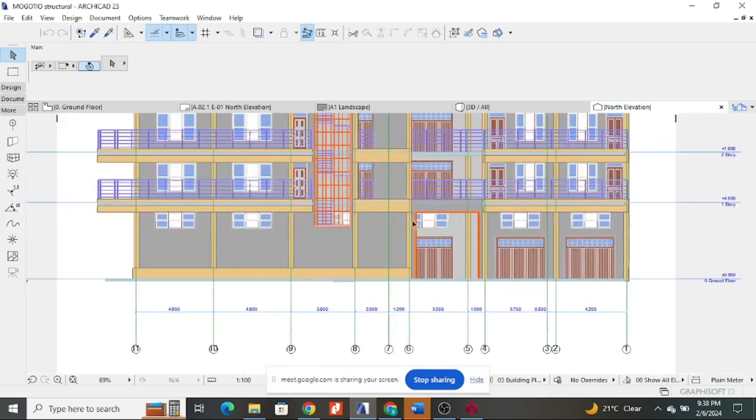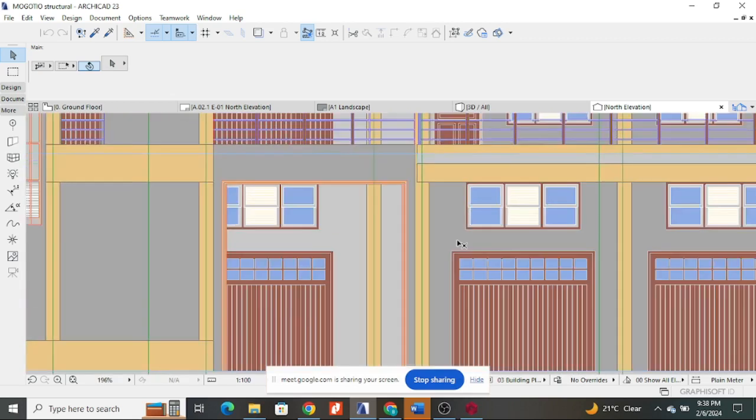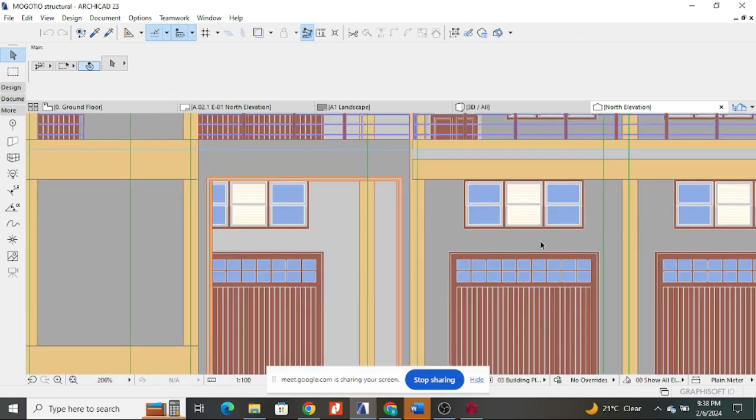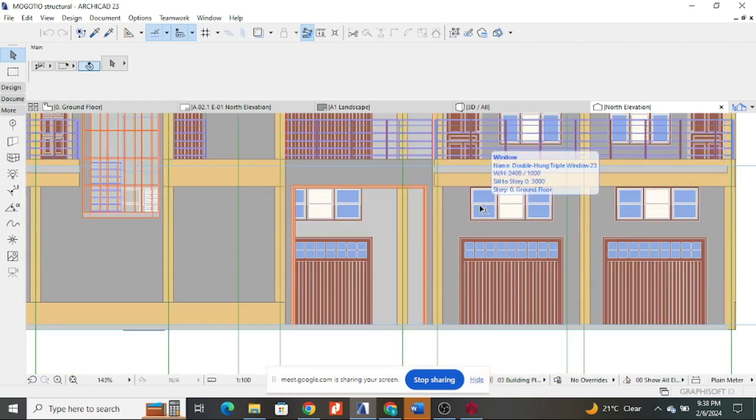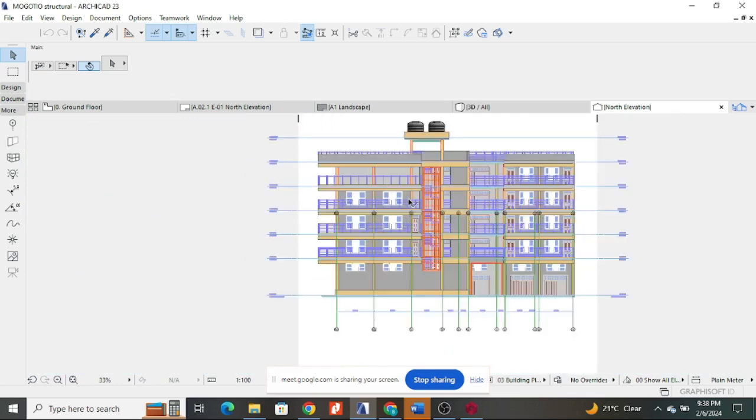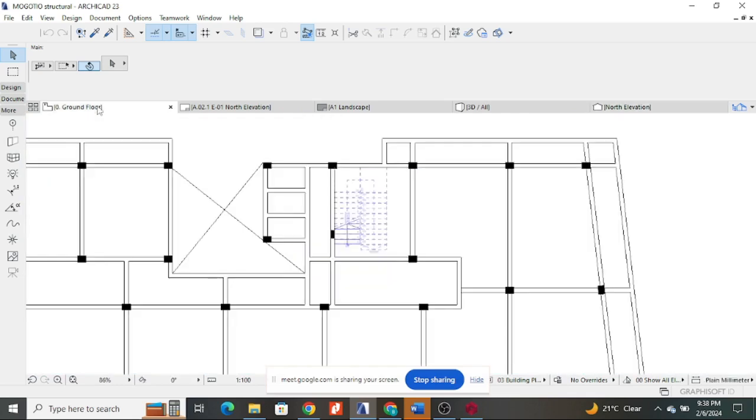So here you design the main beams first, and then these small beams you will design later, because the only weight they are supporting is at where the door is. The beams that are carrying the building are the main beams here. So these ones can be designed later after you design the main ones. I think that explains almost all that I wanted from that section.